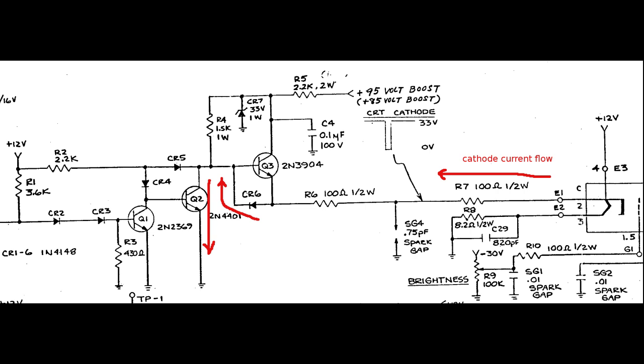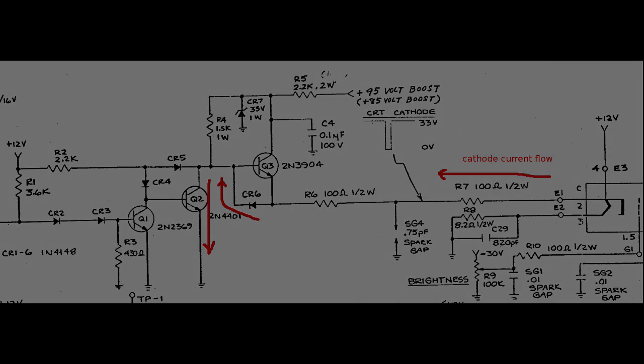But in this case, the PET logic board is already dead and can't have any role in this. Q1 will turn itself off when the 12 volt rail falls below a certain voltage because of the base voltage divider formed by R1, CR2, CR3 and R3.